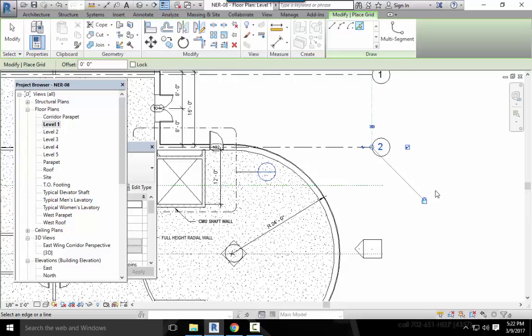Alright, so that takes us through items 1 through 4. Being able to pick lines is certainly an advantage, but you won't always be in a situation where you have geometry in place to do so. In the following procedure, you'll add grid 3 by picking 2 points.